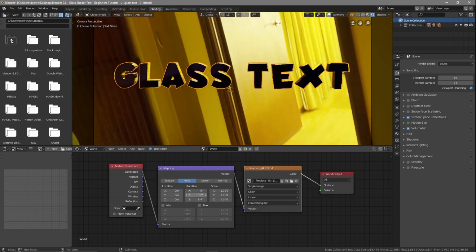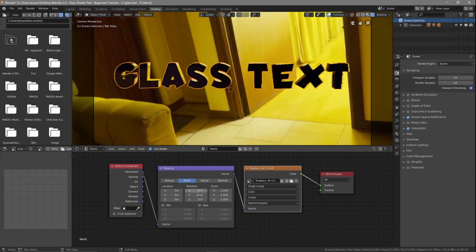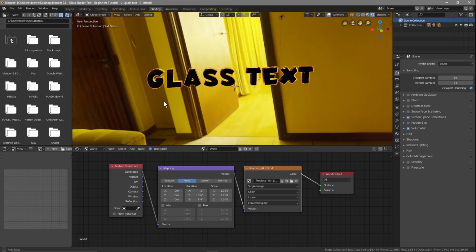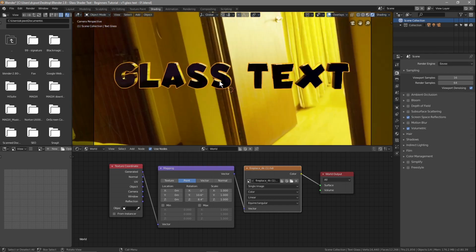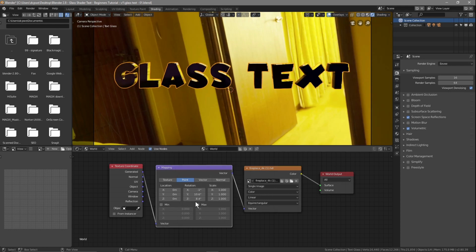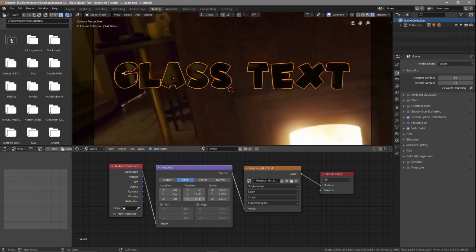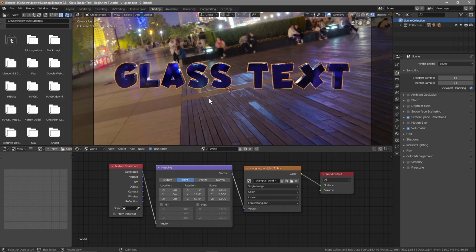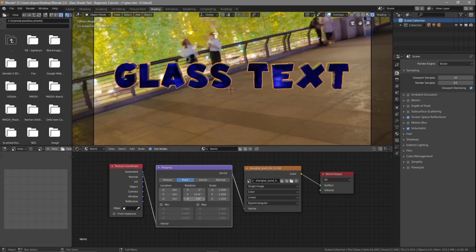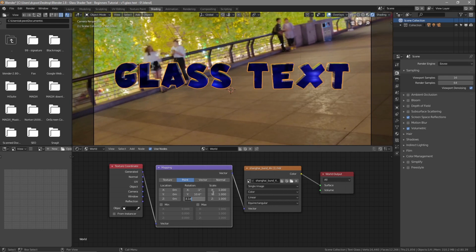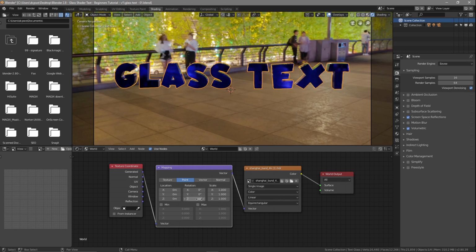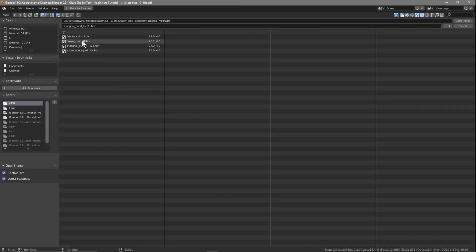So although we're rotating this HDRI image, we won't really see this in the background. We're going to cover all of that up. This is looking pretty dark, right? It's not really illuminating this text very well for this particular font and style. That might be down to the text inside, that blue text, but we'll rotate this around this way a little bit, and I don't think this one's going to work too well for us. So let's open the Shanghai one. Now you can see the blues and all the nice colors coming through, and I reckon this is going to work a lot better. Let's set this X, the Y and the Z to 0 for now. So set all these coordinates to 0. We'll check a few more. So let's try the Flower Road one.